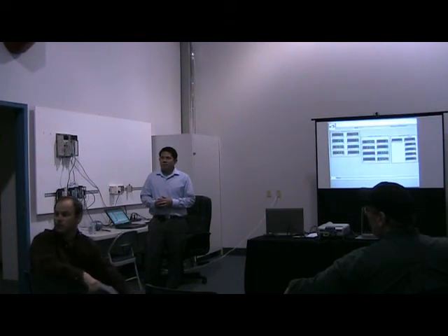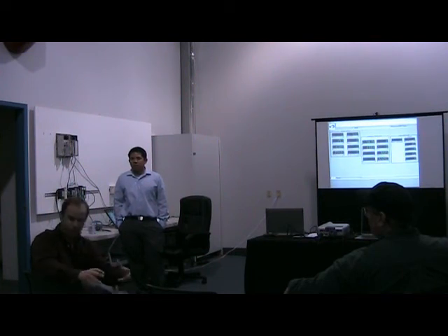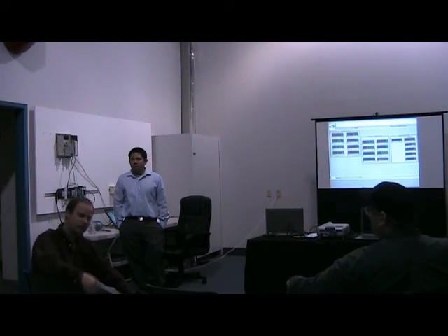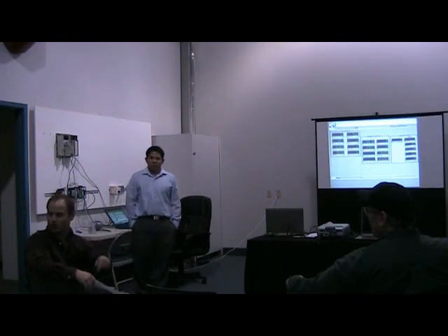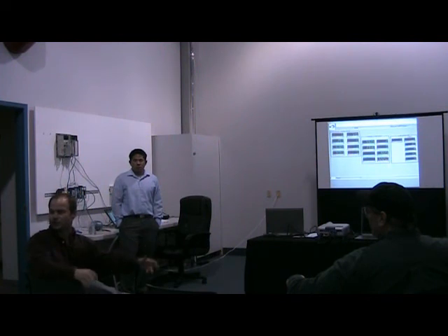Okay, so do you download to it, or do you do it online? Do you do it as you're actually looking? Through the PLC program, you can write the commands and the calibration into the device, all through Modbus, in this case a Modicon write command, and it goes right into that channel configuration. So instead of taking your handheld device, you can just go through the Ethernet software, say, boom. Yes. Like at a greenfield site, you have 20 instruments, initial configuration, type in all the parameters and go boom, and it writes to all 20 devices as long as they have their individual IDs. Address, yeah.